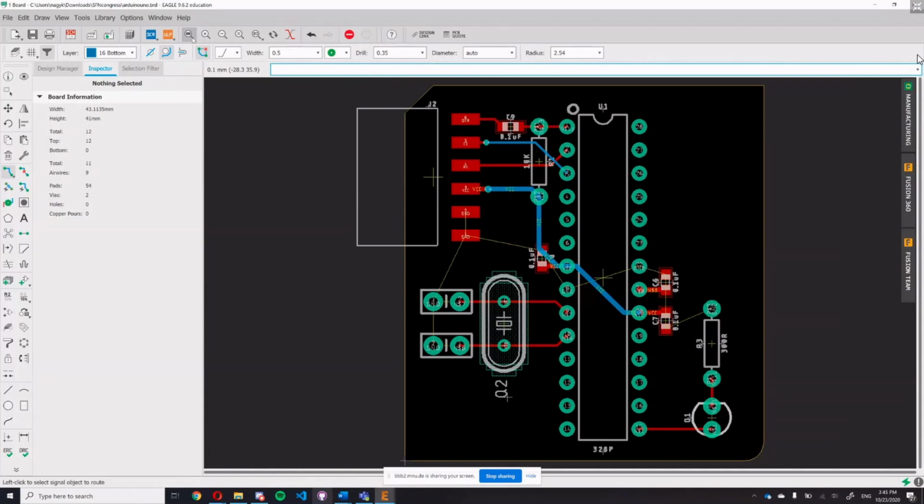I'm sorry to interrupt. I just want to add something about VIAs and SMD components. You might have guessed, but I will just say it anyways. As you can see, the SMD component near the VCC, like the capacitor in the middle, the blue line goes kind of through the component. And that's totally fine because, like Jakub said, the SMD is on top of the PCB and the blue line is below it.